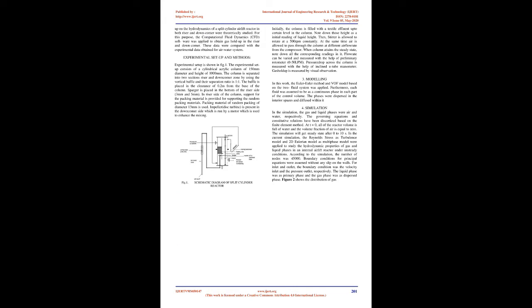Since many reports discuss the air-water system, in which air is used as the dispersion phase and water is used as the continuous phase, some reports also explain salts, alcohol, surfactants, and emulsions, which show different behavior when their concentration is varied. Hydrodynamic studies in the split-cylinder reactor mainly consist of examination of gas holdup, liquid circulation velocity, flow